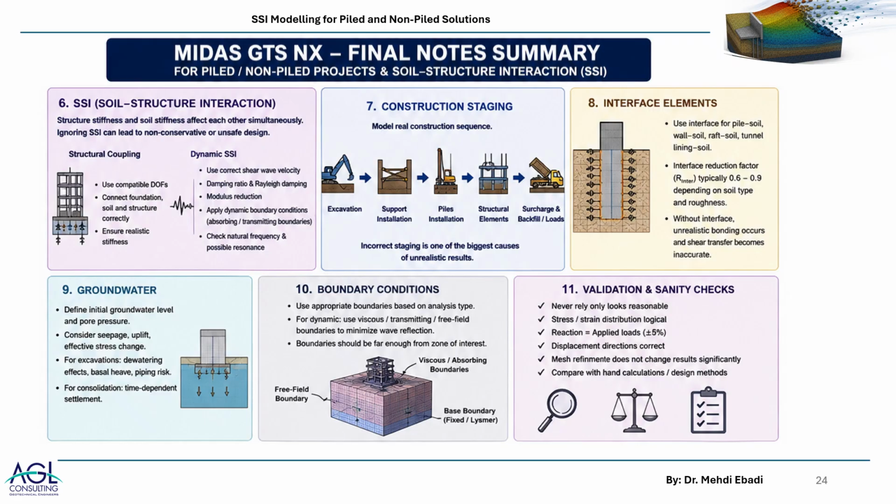And for interface elements, usually when you find that properties of the soil at the interface in real practical condition, assuming that you're following the design, is lower than the soil media, then you need to use the interface.